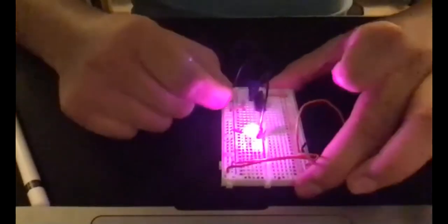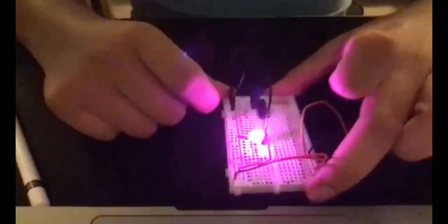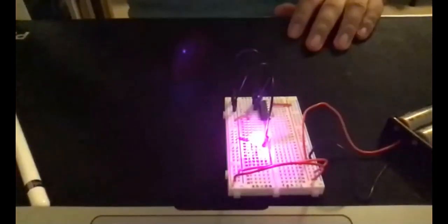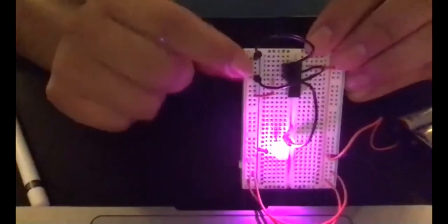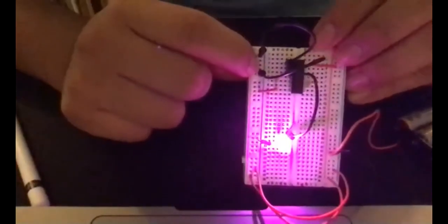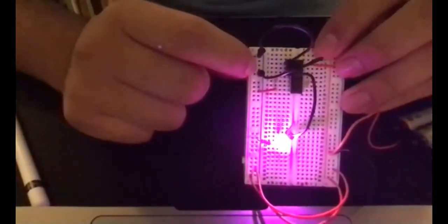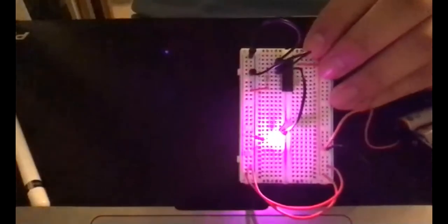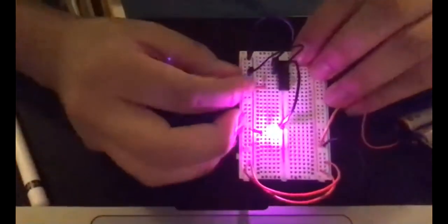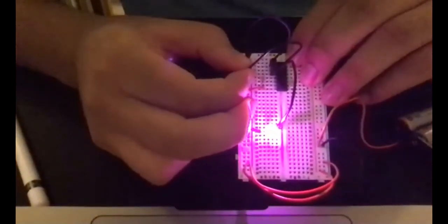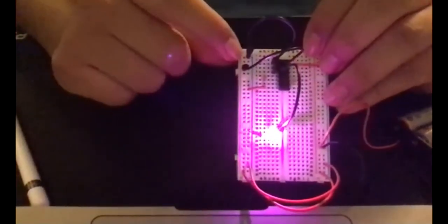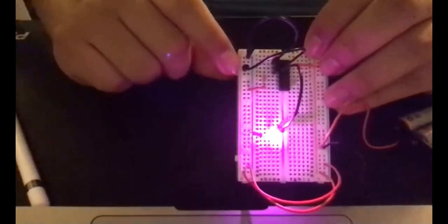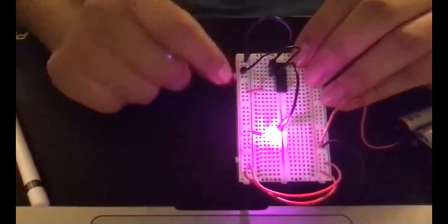Okay, so that's just to show that the LED is on. So hopefully you can still see me moving around these inputs. Like I said, for a NAND gate, when you have 2 lows, both of these inputs here are connected to a ground. So that basically means your inputs are 0 and 0. And with a NAND gate, when you input 0 and 0, your output is a 1. So if we were to switch one of these to the positive, it still remains on because 0 and 1 in a NAND gate is still a high.